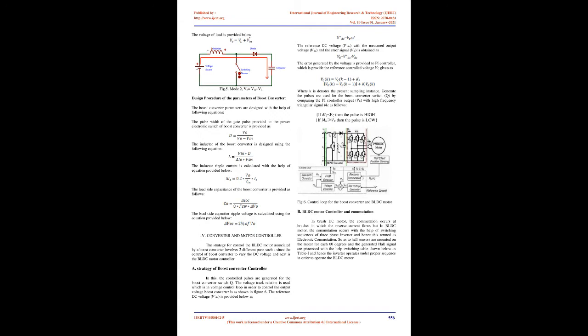D. Synchronous generator. The synchronous generator is coupled with the BLDC motor so that it can generate power when the vehicle is in running state. The generated power is provided to an uncontrolled diode rectifier, which provides DC supply to other electronic vehicle loads such as cooling/heating system, music system, lighting system, etc.